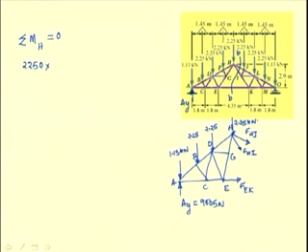The first is the counterclockwise moment of the force at this joint F, which is 2250 times this distance, that is 1.45 meters, and this is a counterclockwise moment. So, it is positive, plus the moment of the applied force at D, which is again 2250 into 2 into 1.45, which is the moment arm.